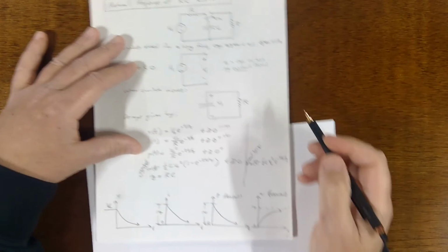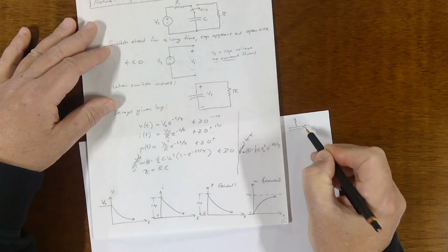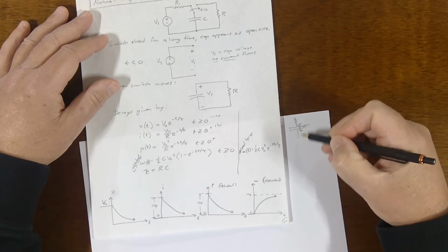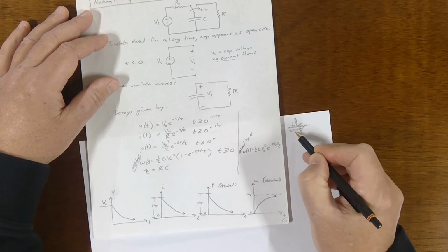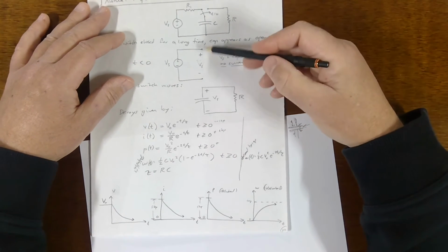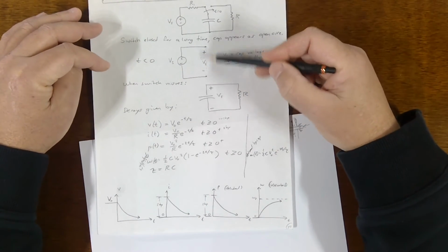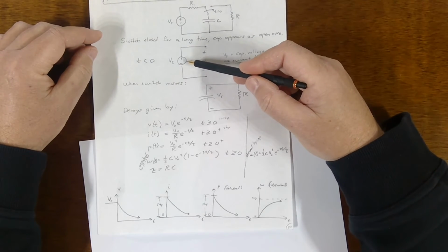Because caps are open circuits. I mean, there's an insulator in here. They don't conduct through. You know, this doesn't happen. The current does not conduct through here. The current comes to the plates and stops and leaves the plates. So it doesn't go across. So they are an open circuit for steady state, and that's exactly how they behave for steady state voltage.